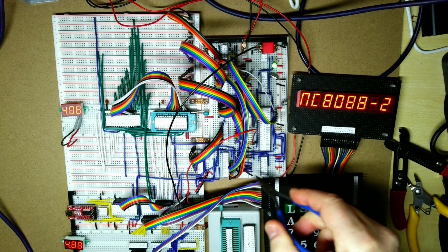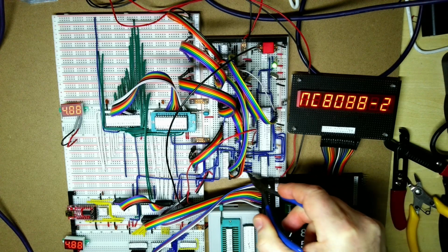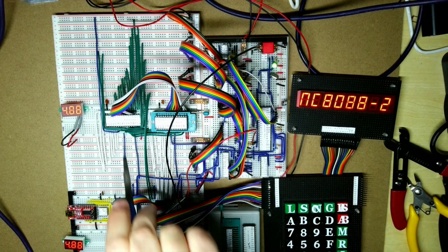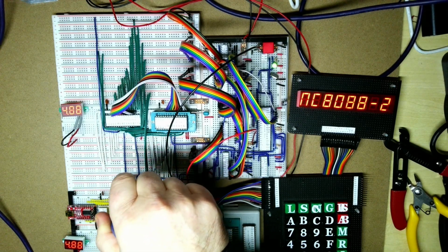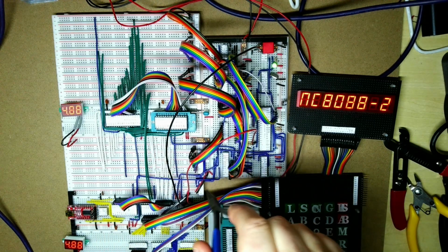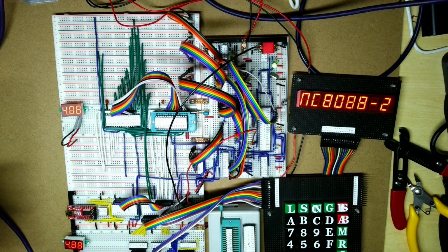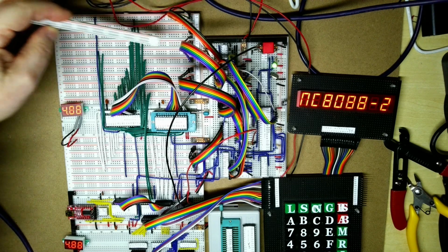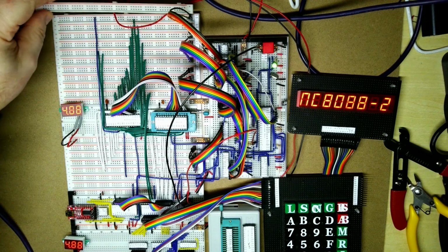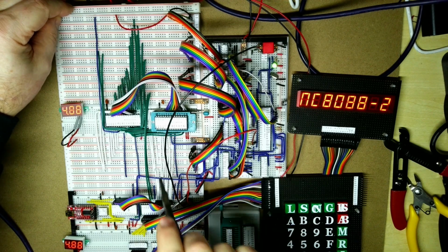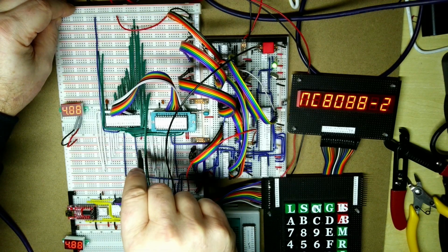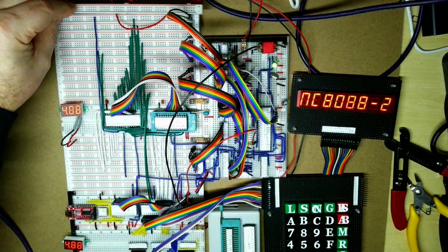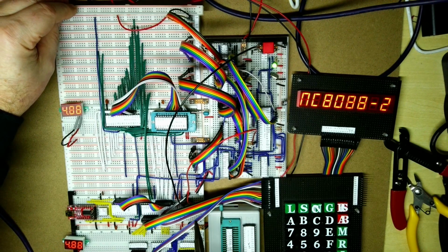We're going to have to wire in the IO read and IO write from here round to here. Now at the moment, the RAM and the ROM is using the two lines here, which are currently memory read, memory write. Now these are going to become IO read and IO write. So what we're going to need to do is add an extra bus at the top here. I'm going to put the memory read and memory write at the top here, and then these three lines here, so there's two memory reads and one memory write, are going to need to go round up to the top there. But because these ones down here are going to be changing to IO read and IO write, I don't need to change anything down here.